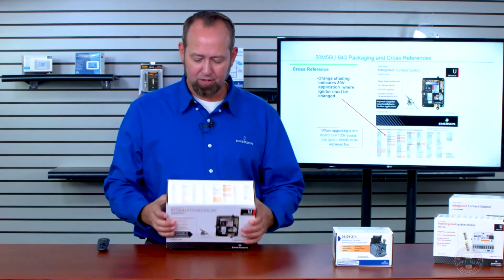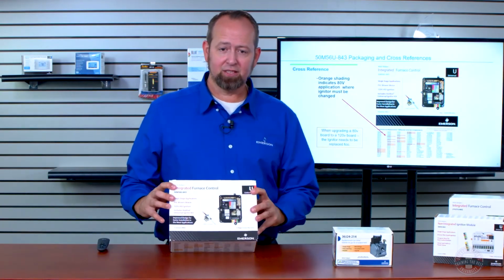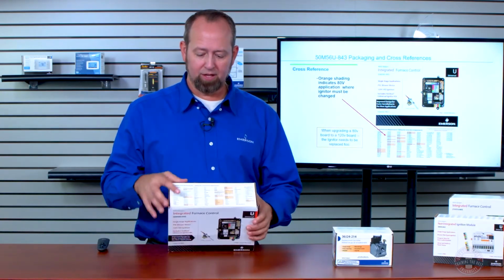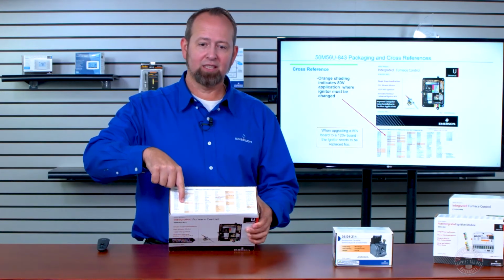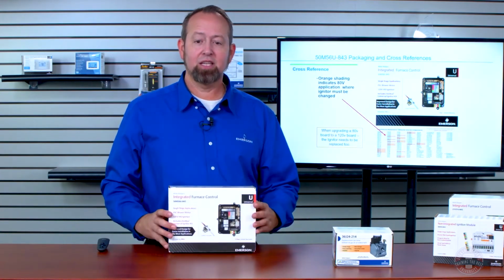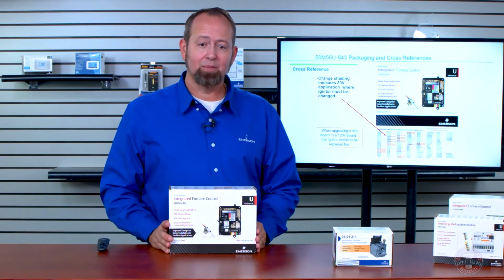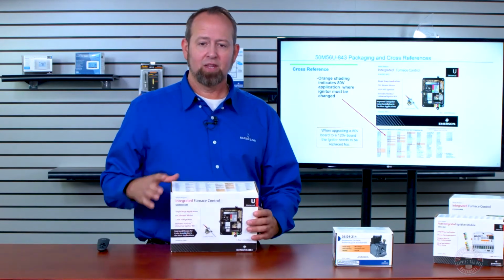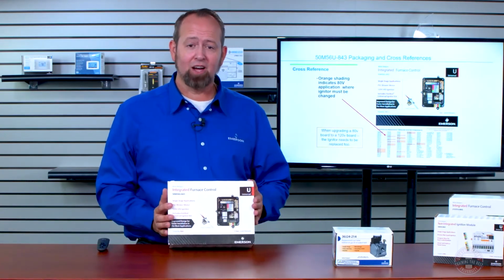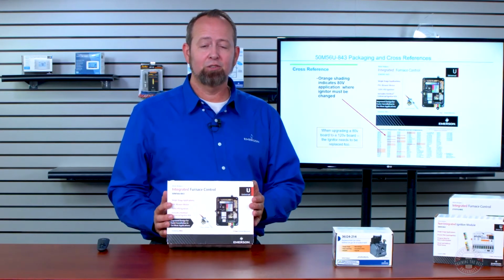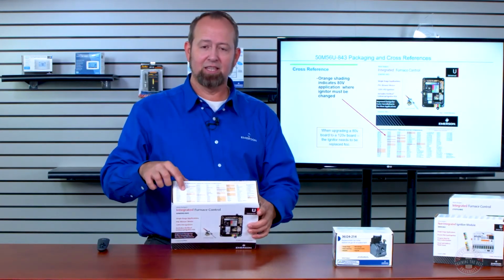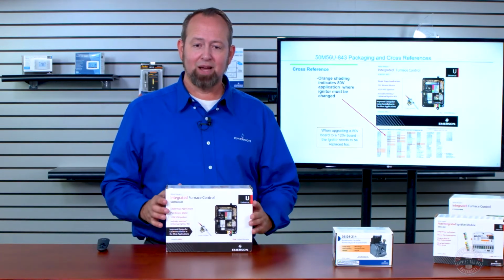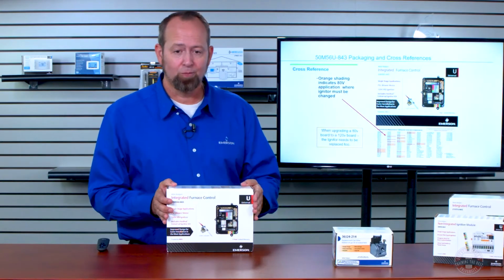And so anytime you was to take the 50M56U and replace it with a board that the old number is in orange, that would mean that the igniter needs to be replaced at the same time, because the existing igniter, the ones in orange, have 80 volt igniters. That is why we include the hot rod igniter with the 50M56U, is because there are applications that igniter must be changed out so that it's 120 volts and it matches the 120 volt universal control.